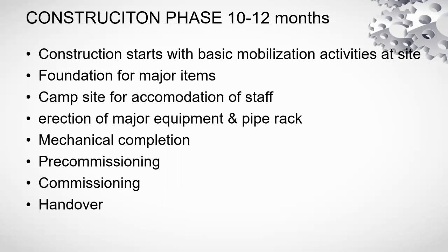Then comes the stage wherein mechanical completion is done. When I say mechanical completion, it involves piping connections, equipment connections, and all electrical and instrumentation connections. So this is a major stage from the construction point of view, where mechanical completion is declared, and a major payment milestone for the stakeholders.